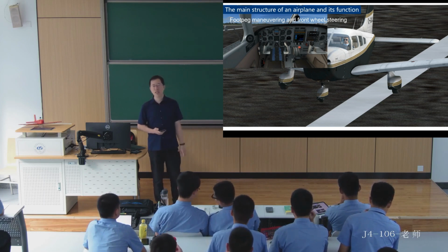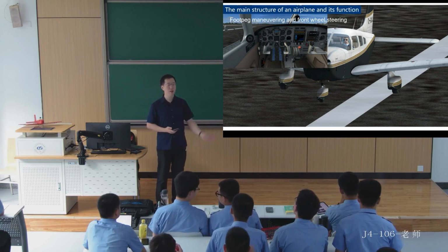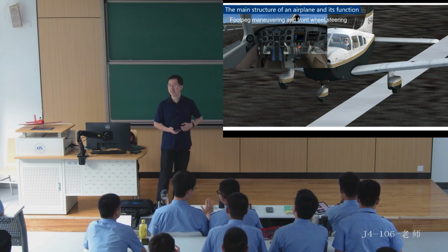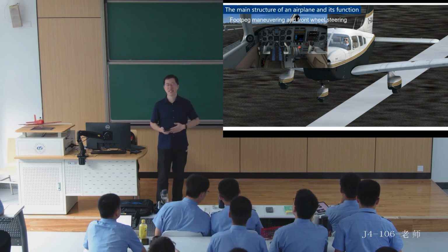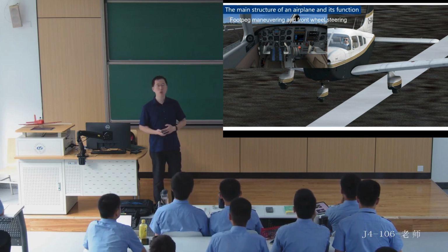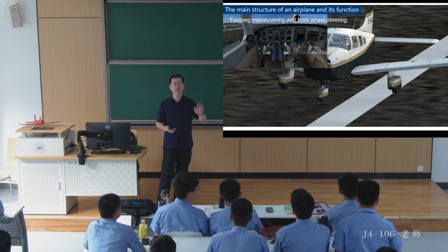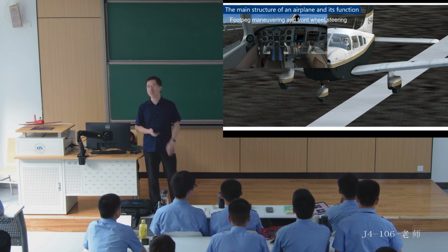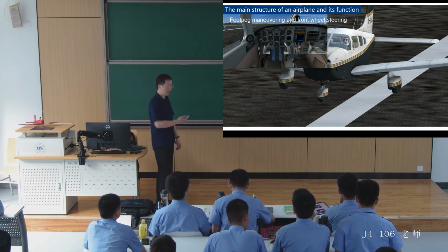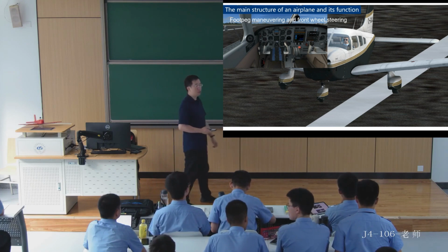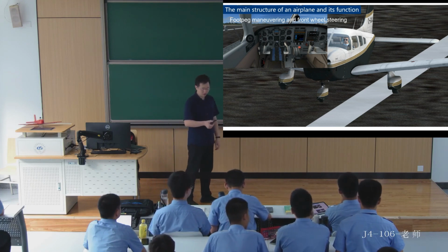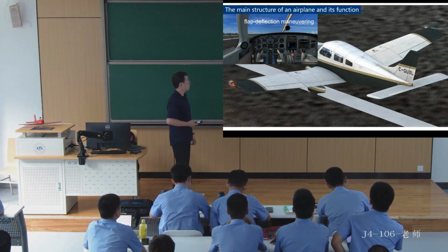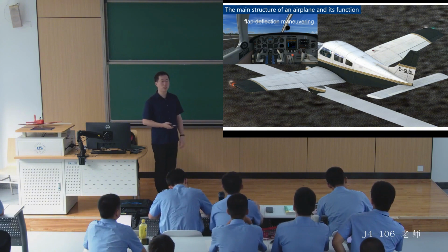So, how do we adjust direction at low speeds when taxiing an aircraft without nose wheel steering? We should use differential braking. That means pressing the left and right pedals differently to control the direction of ground taxiing. I hope everyone knows this. It's basic common knowledge. Now let's talk about the operation of the flaps. How do we operate the flaps?